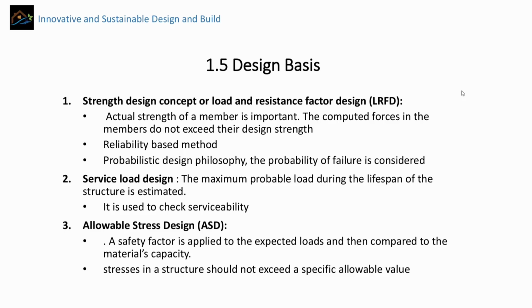And the third one is allowable stress design, and this comes from the idea that the factor of safety is applied to the expected loads, and then compared to the material's capacity. Stresses in a structure should not exceed a specific allowable value.